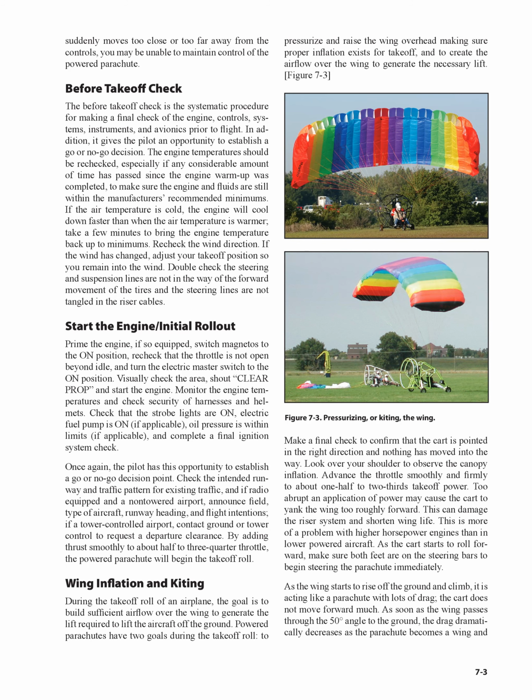Before takeoff check. The before takeoff check is the systematic procedure for making a final check of the engine, controls, systems, instruments, and avionics prior to flight. In addition, it gives the pilot an opportunity to establish a go or no-go decision. The engine temperatures should be rechecked, especially if any considerable amount of time has passed since the engine warm-up was completed, to make sure the engine and fluids are still within the manufacturer's recommended minimums. If the air temperature is cold, the engine will cool down faster than when the air temperature is warmer. Take a few minutes to bring the engine temperature back up to minimums.